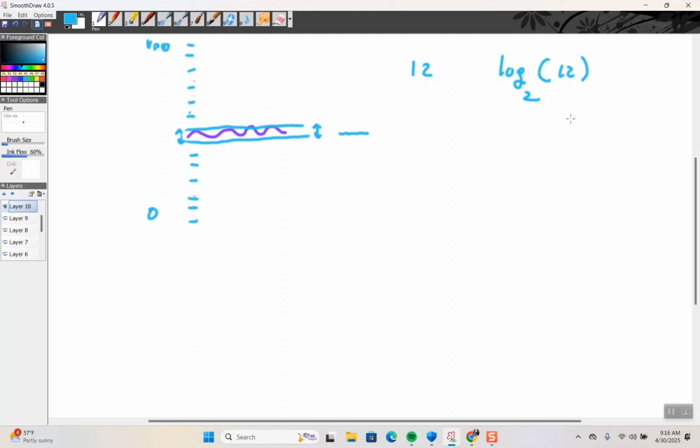So, what, 2 to the 3? A 3-bit system gives you 8 levels. A 4-bit system gives you 16. So we're in between 3 and 4. What you're going to be finding is what the best frequency is and what your effective number of bits is for the project.